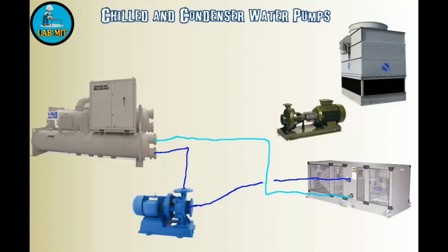So now we've pretty much completed the chill water piping. The water comes into the chiller, comes out cold, runs through our coils. This could actually branch off and probably hit multiple air handlers all throughout the building. But once they come back, they'll come back on the chill water return. And this is, let's go ahead and label that. This would be the chill water return. And this here is the chilled water supply. And this here would be the big loop. It would go through the pump, through the chiller, and back to the air handlers and so forth.